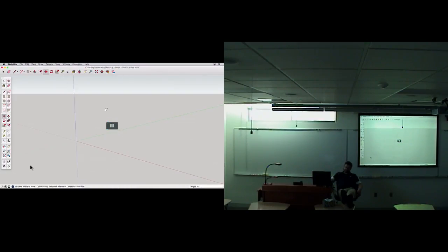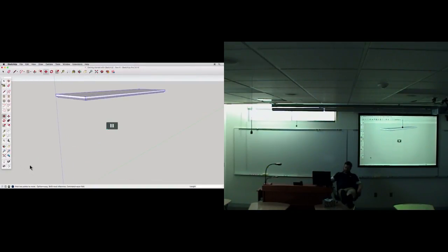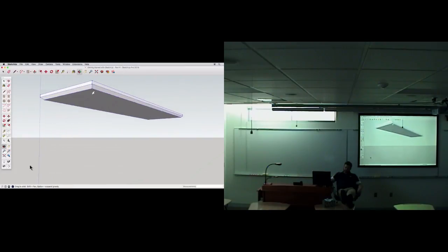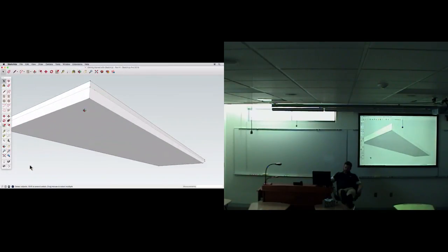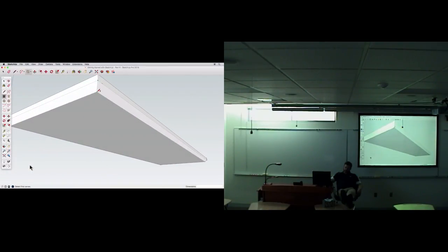Given our top is 1 inch deep, that will give us a total table height of 38 inches. Orbit underneath to start drawing the table legs. Draw a rectangle, starting from this corner, that we can pull into a leg. However, before using push-pull, let's say we change our mind and we want the leg to be inset from the edge instead. If we select and move this surface, however, it begins to warp the tabletop.